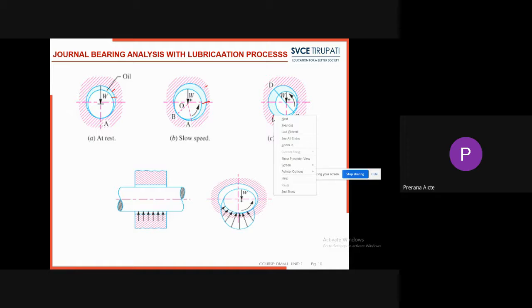See here, okay? So why? Because the bearing axis and journal axis are different. See here, this one is called the bearing axis, and this one is called the journal axis. This gap, the distance between the journal axis and bearing axis, is called eccentricity. So based on this eccentricity, you are going to get more gap.